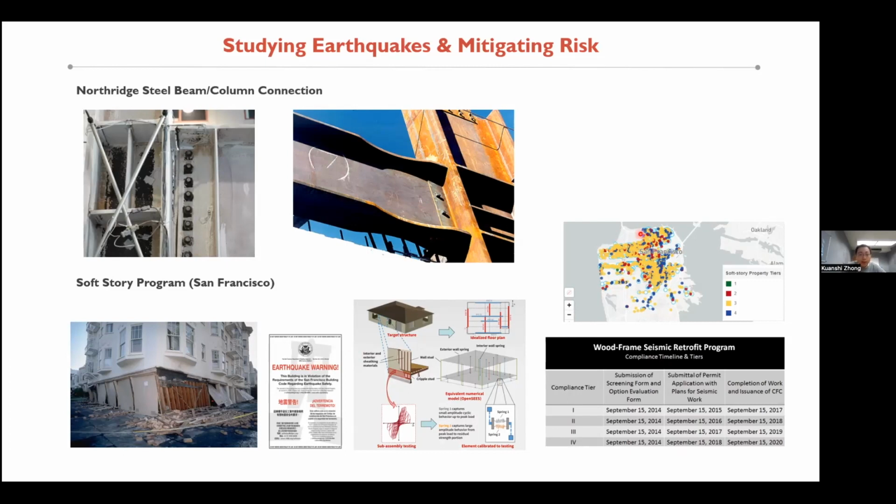Here on the top right figure, you can see the identified soft-story buildings at different vulnerability levels. Through this study, structural engineers try to target those weak buildings and build detailed models to analyze how badly the structure would behave, and what the potential retrofitting strategies would be, specifically affordable strategies for low-income families in the city to retrofit their weak buildings.